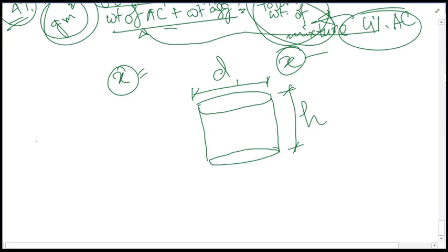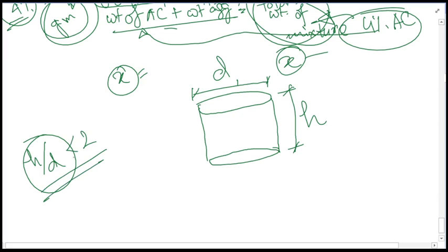In the materials sessional, you have seen that in a cylindrical test for applying loads, we need to maintain this ratio less than 2, because there might be adverse effects otherwise. Otherwise we have to use different correction factors, as you have seen there, because of platen restraint effect and the height by diameter ratio. But in this case we have no problem, because our diameter will be well larger than the height, so no issue of h by d equals 2, or rather it will always be less than 1. You will be watching there.